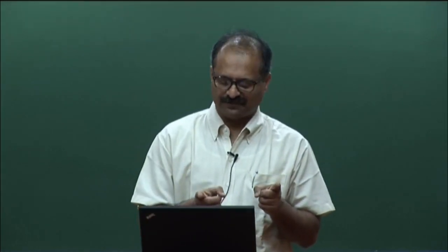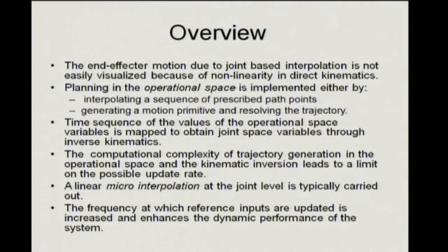So far what we are saying is that once you have found out what the different values are, you just do motion planning on each axis. Now it is not necessary that if I move halfway along theta 1 direction and then halfway along theta 3 direction, so on and so forth, or halfway along all the directions, then I will actually move halfway between this point and this point. That is not guaranteed. In fact, in most cases it won't be true, because of nonlinearity. So there is a need to program directly in the operation space, that is the space in which I am operating.